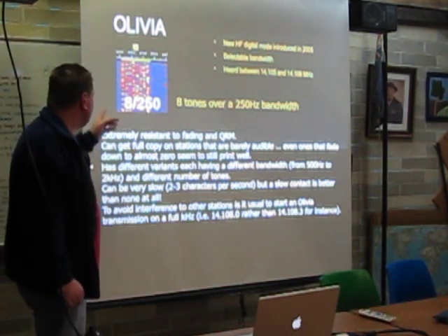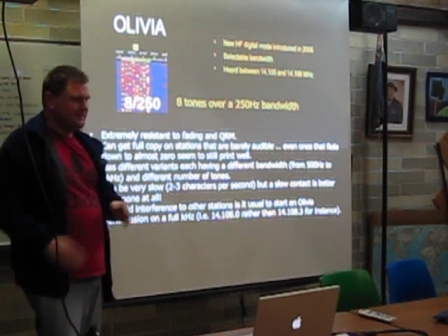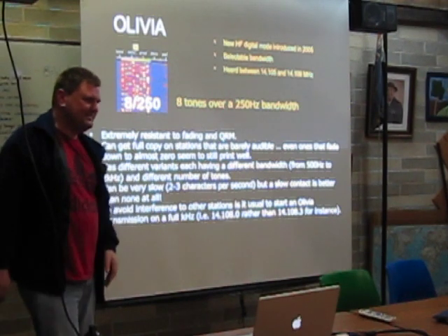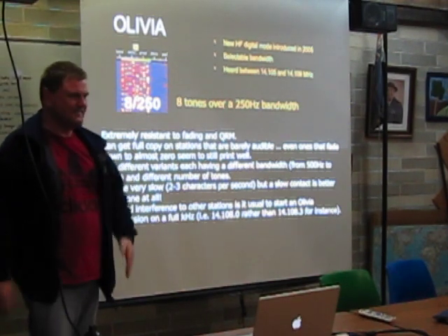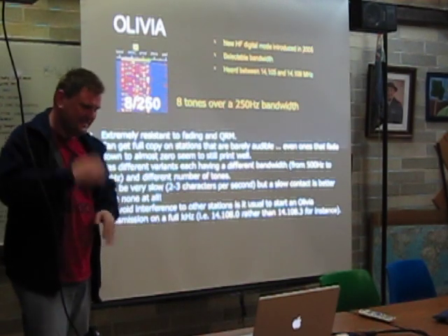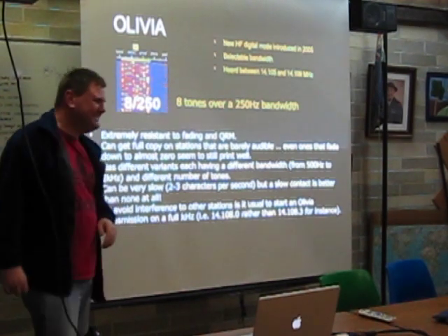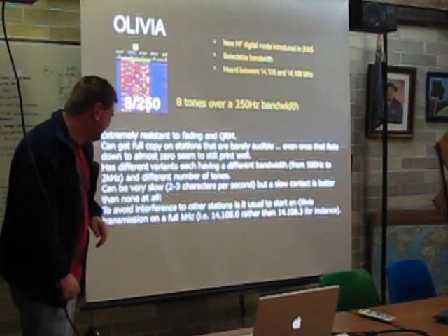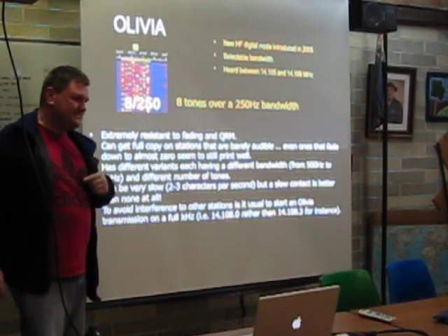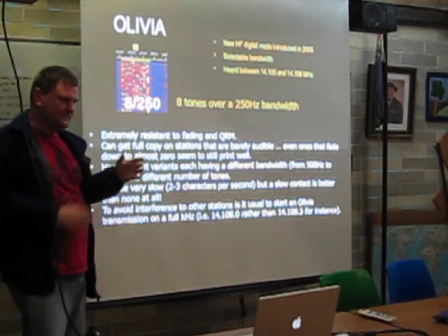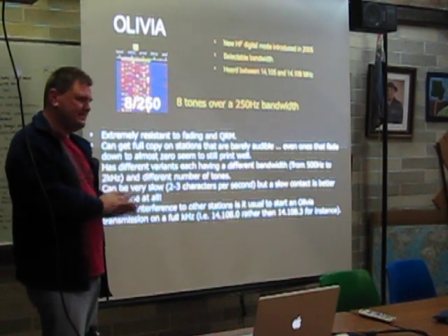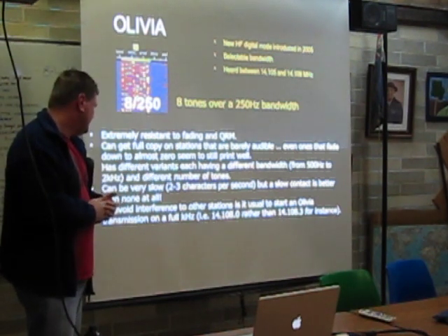This mode is extremely slow, so it'll send 3 characters and then another 3 characters and another 3 characters, and you go and make a cup of tea, and then maybe the guy's finished his over. Suits perfectly to my typing. So it's very slow, but it makes very heavy use of what I call forward error correction, where it sends a lot more information than it needs to in order to get the message across.